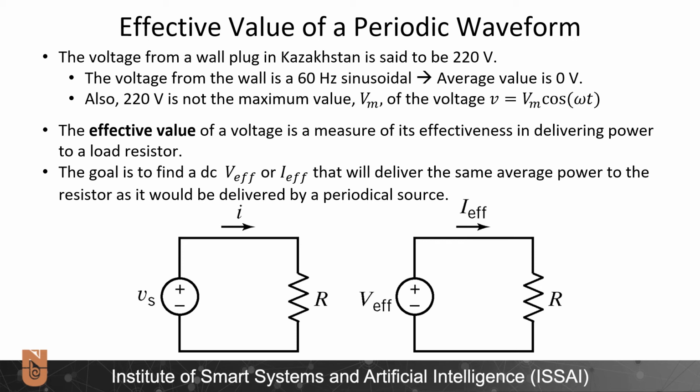So what is this 220 volts? 220 volts is not indeed the amplitude of the sinusoidal waveform. It is the effective value of that waveform. The effective value of a voltage is a measure of its effectiveness in delivering power to a load resistor.